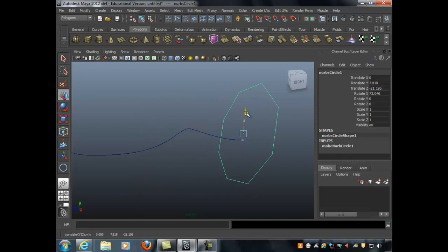Now, if I don't line the sight up onto the curve, it won't snap to it. All right? You have to move it so it lines up onto the thing, and then click it one more time, and then it'll snap to it. And you're probably going to say, how does that work? And my answer to you is do it until you understand it. So you got to line it up and sight it up, and then you can get it to snap.